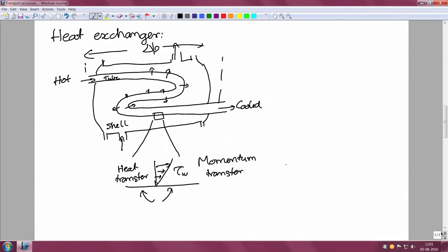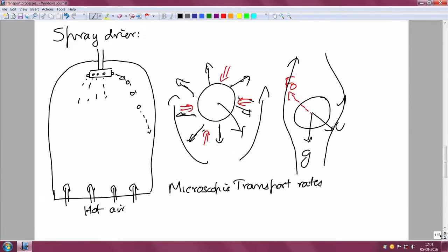Dimensional analysis enables you to make the number of parameters much smaller using dimensionless groups, because if you express everything in terms of dimensionless groups, you can reduce the number of parameters. Similarly, in this case of the heat flux and the mass flux, all of these depend upon the properties of the fluid, the air around, the specific heat, the conductivity, the humidity and so on. They depend upon the latent heat of what is to be evaporated. And so you end up with a large number of parameters.